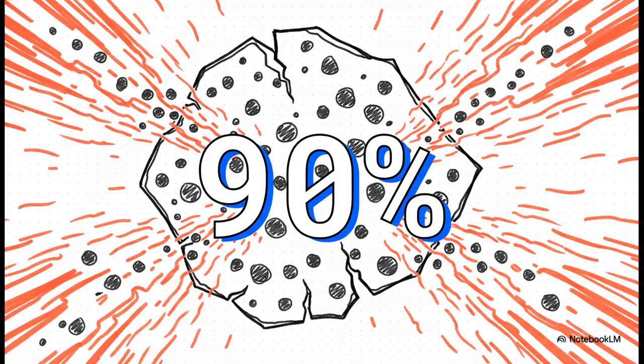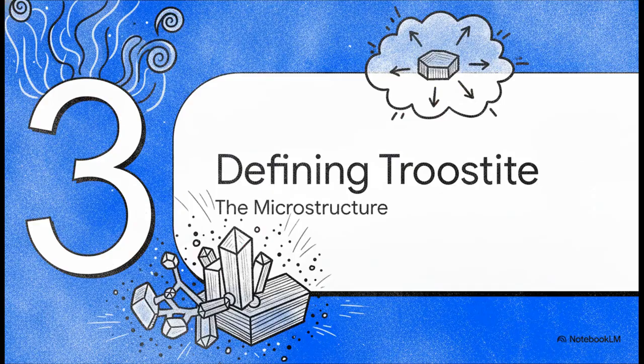So what actually happens at that temperature? Well, we see a staggering 90% of the remaining carbon just abruptly release from the Martensite structure. Remember, back in stage 1, only about 10% of the carbon precipitated out. But here, the heat literally forces that remaining 90% to completely rush out of its trapped state. It's this rapid, microscopic evacuation of carbon, and it fundamentally changes the entire nature of the steel. And that mass evacuation creates something entirely new.